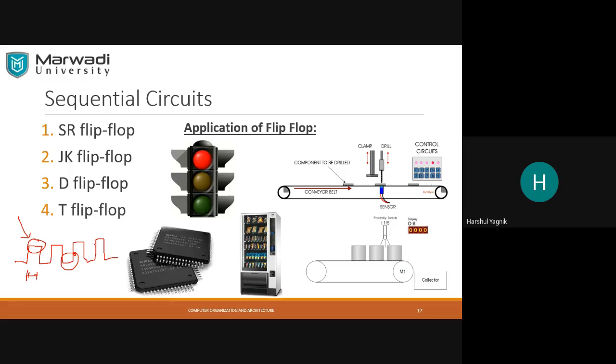Flip-flops are edge triggered. So there are two edges, one showing a transition from 0 to 1. That edge we call a rising edge. And another edge showing a transition from 1 to 0, that edge we call a falling edge. Rising edge and falling edge. So two kinds of triggering are possible. One digital IC will be fabricated based on any one of these. Okay?